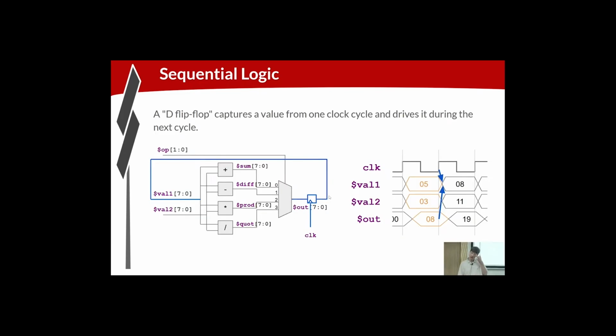So everything that we do in transaction level Verilog, TL Verilog is going to manage the sequential elements for us, the flip-flops. Okay, everything that we're going to imply in our design is a D-type flip-flop, which is simply taking the input and carrying that forward to the output. There are other types of flip-flops that incorporate logic functions. Logic synthesis is very good at taking the functionality of our circuit and optimizing it to choose logic gates that are optimal. If it's optimal to choose a different flip-flop type that incorporates some of this logic, logic synthesis will do that.